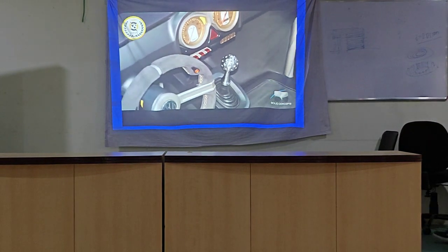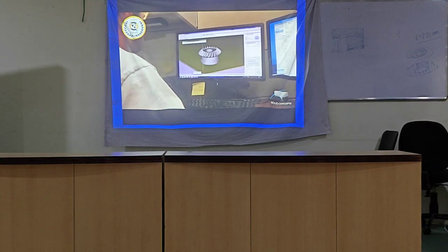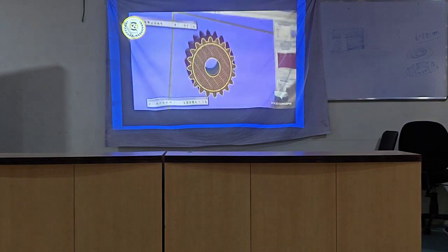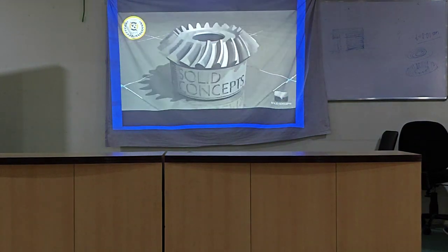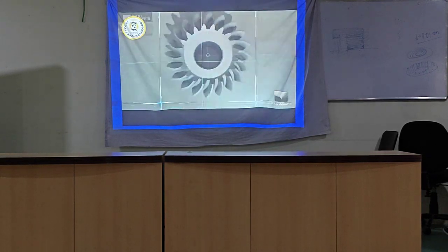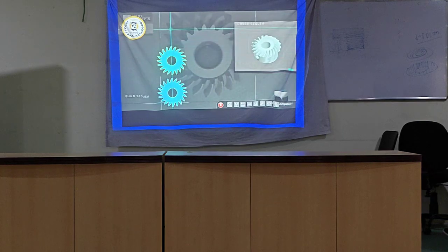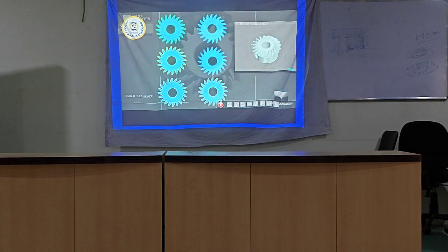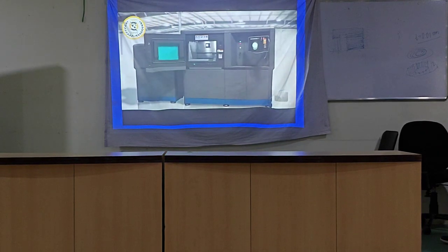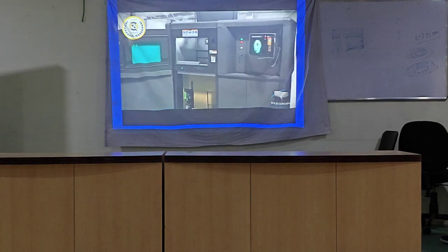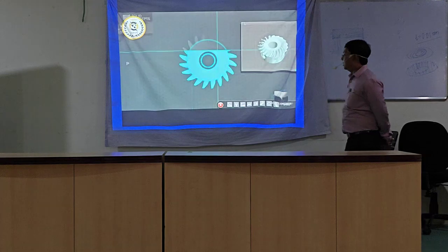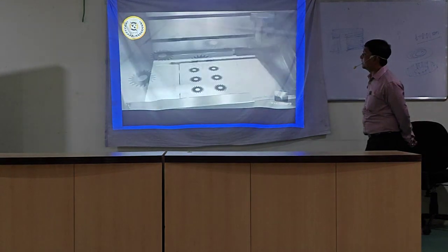The DMLS process begins in the same fashion as other layer additive manufacturing technologies. A program takes 3D CAD data and mathematically slices it into 2D cross-sections. Each of these sections will act as a blueprint, telling the DMLS machine exactly where to sinter the metal material. The data is then transferred to the DMLS equipment. So this is the machine, though it is an animation kind of thing.